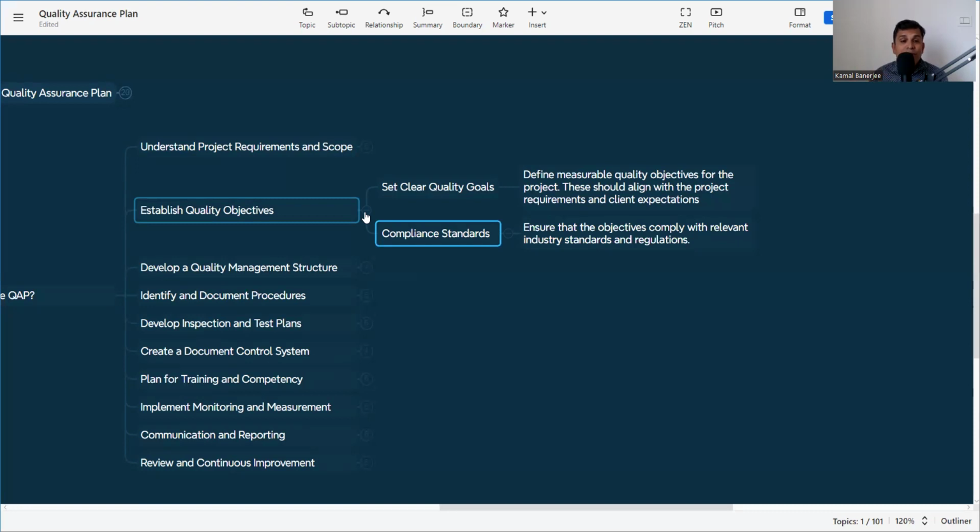Then we need to fill the material, and what will be the height of the filling. Maybe 200, 300, whatever, as per the requirement. And what is the frequency of testing? That means in maybe 500 square meters, three tests we need. And what is the degree of compaction? Maybe 98. So these are the parameters for each and every activity we need to find out, and we need to define the scope of work.